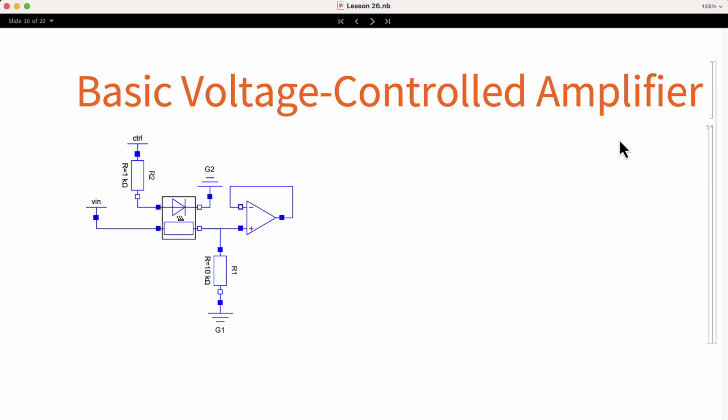So far we have focused on oscillators. Now let's try to create other types of modules to complete a basic synthesizer voice. In the following diagram you can see a very basic voltage control amplifier or VCA that is built with a vactrol. If you remember the previous lesson, a vactrol can change its resistance based on a control voltage. The circuit that you see is a voltage divider.